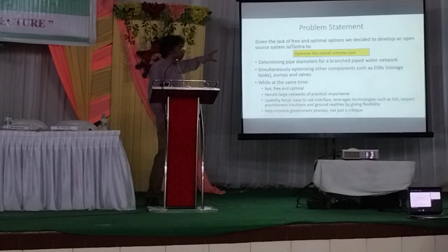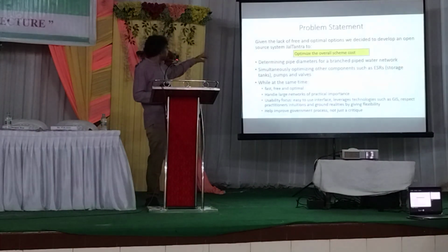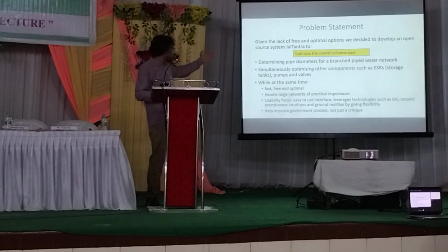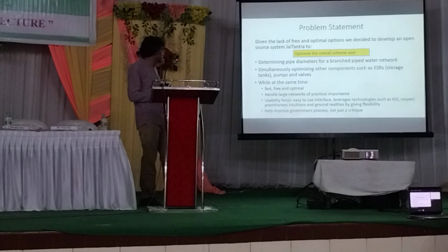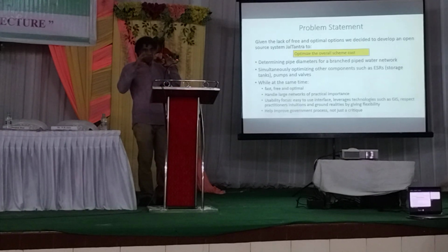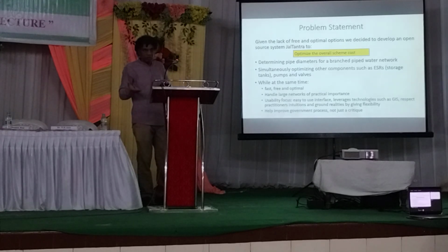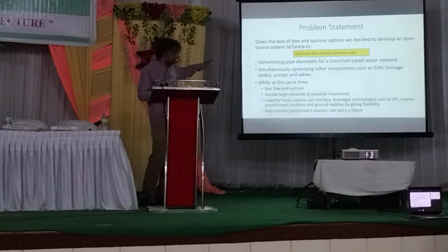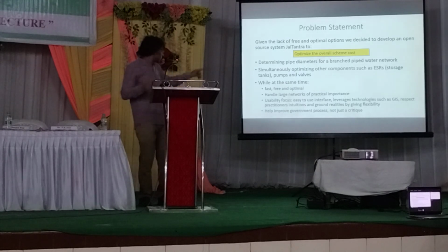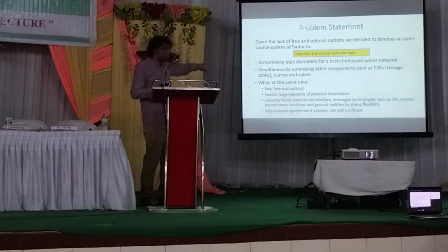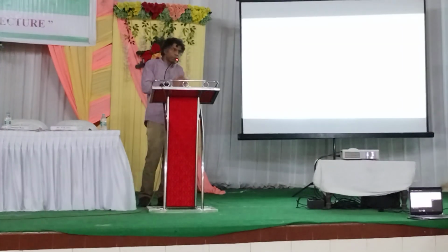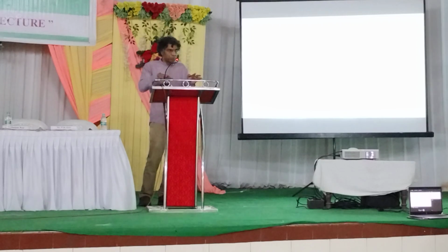So then we came up with the problem statement that we come up with a free and optimal design system that will optimize the overall system cost. And the first part of it was because in a rural network, mainly the pipes constitute more than 50% of the cost. So in the first version of the problem, we only focused on pipe diameter, which is what was typically optimized by engineers. The other things like ESR location and pump were all being done ad hoc. But we said let's make it part of the optimization process. Let's do a simultaneous optimization.